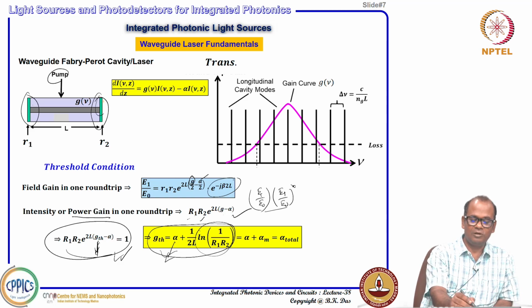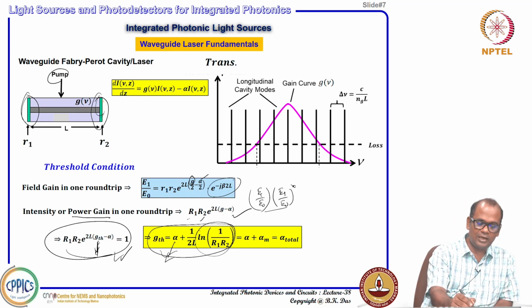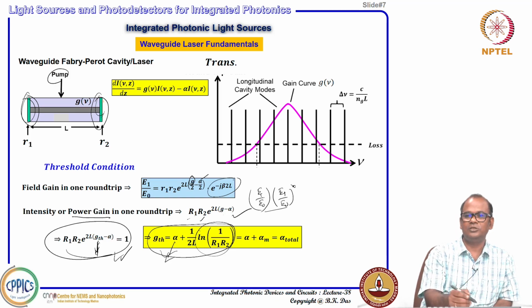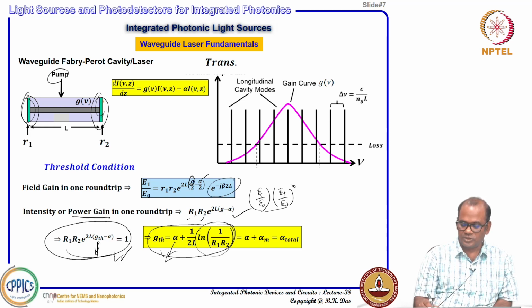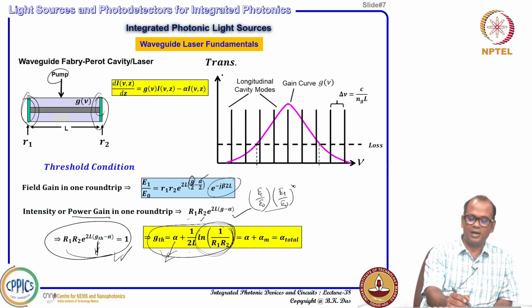When the signal goes to this lumped point, at one particular spot, you lose something, and then it comes back, and again at the mirror here you lose something because it is not completely reflected. That loss is the total loss for two reflections, and it has been divided by 2L, meaning you have distributed it per unit length, distributing the mirror loss into the entire cavity.